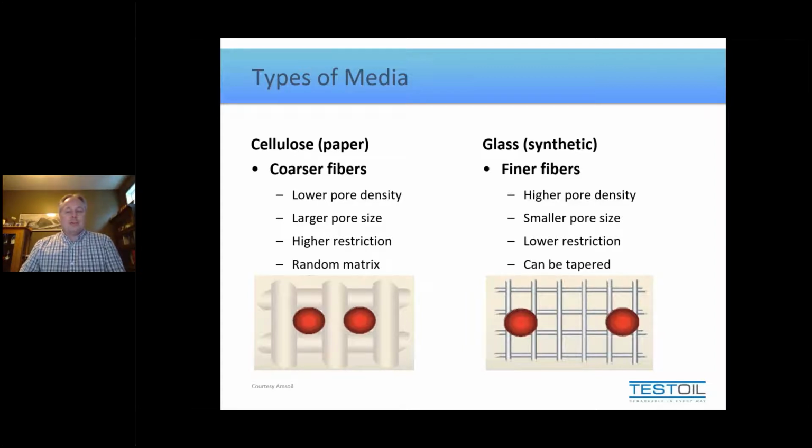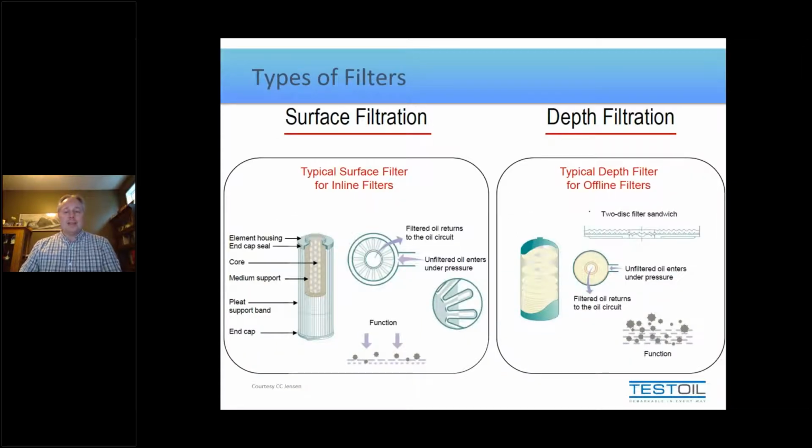So one quick note here is these are only media types. There are also 2 different filter types, and basically they can either be called surface, or what many of us usually refer to as pleated, because that's exactly how they're constructed and what they visibly look like, versus the other style called depth, or what many of us refer to as stacked, because again, that's how they're constructed and that's the visible aspect to them. But the big difference between a surface and a depth filter is that a surface filter is one piece of media and the oil flows through the surface of the media, which is why it's called the surface style of filter. But you get that one layer and one layer only that the oil passes through.